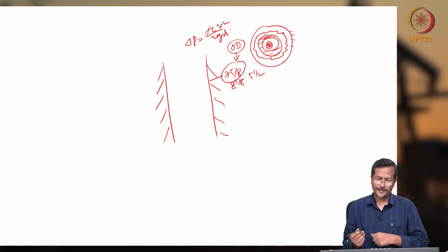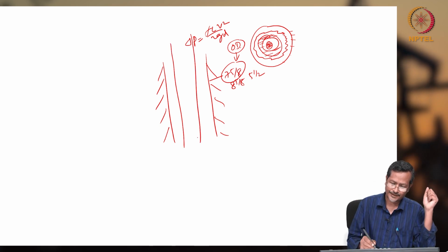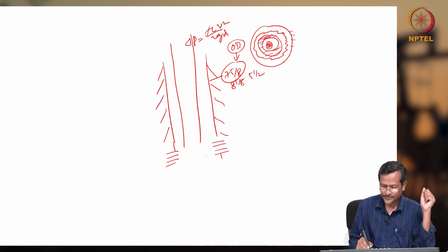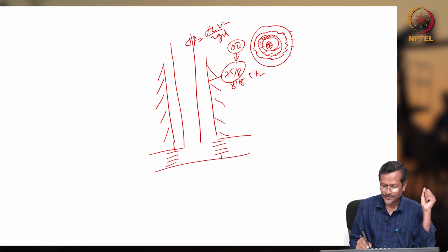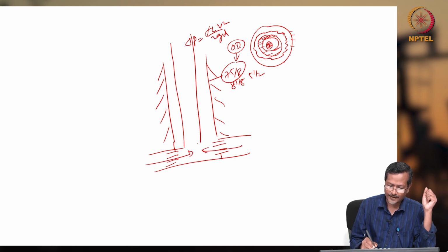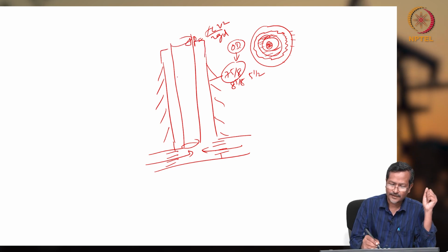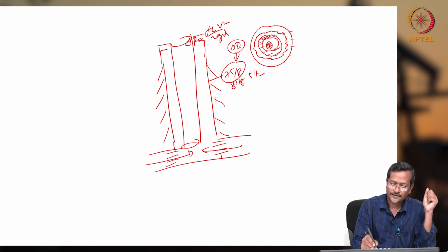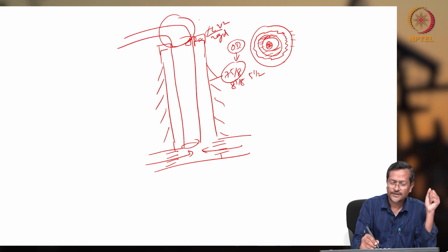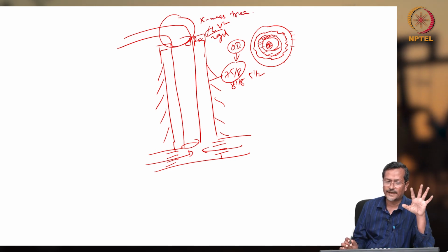Now inside casing there is tubing, and you will have your perforations. Okay, and we are assuming this is your oil and gas zone, and you are perforating this one, and you are getting your production from here. Okay, so from here there will be one casing head, you can remember, then it will be diverted, and there will be Christmas tree. This is a whole mechanical arrangement.